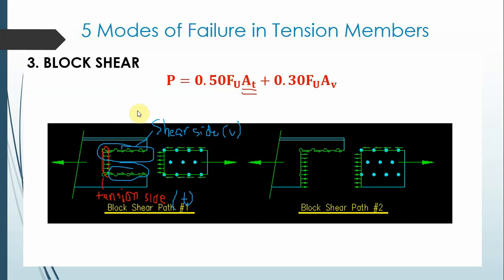So for our block shear, there are different paths of failure. It can detach from the bolts, or it can be from this point here up to this point. Then we analyze what the area is here and here. For this one, the shear area is multiplied by 2, whereas here there is only one: one for tension and one area for your shear. Okay, we will analyze that.